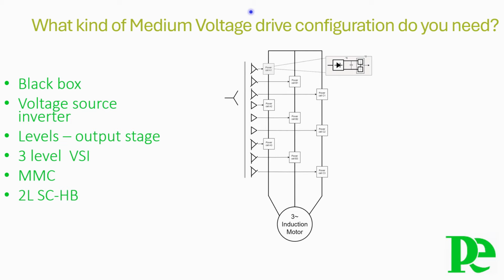The result of adding up the output of multiple low voltage power cells is a high quality output voltage providing less than 1% induced torque ripple, no need for an output filter for motor cable lengths even up to 2 kilometers, a high reduction in common mode voltage, no derating on new or existing motor, no voltage spikes at the motor thanks to small output voltage steps, thereby indeed allowing the use or the reuse of a motor with standard insulations, ideal for retrofit.